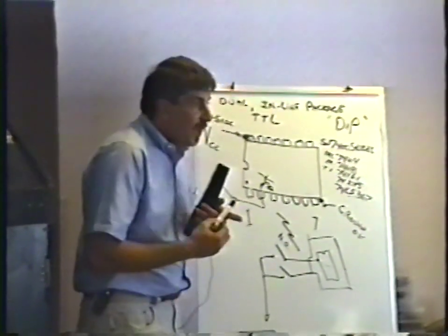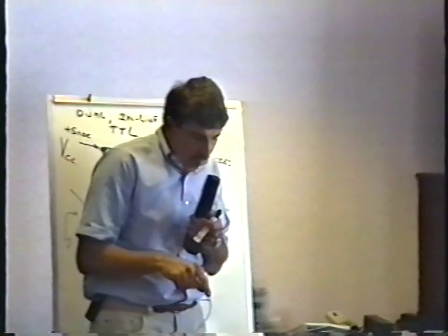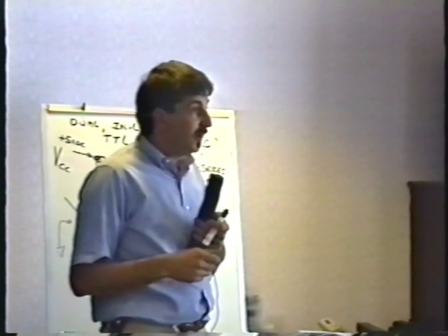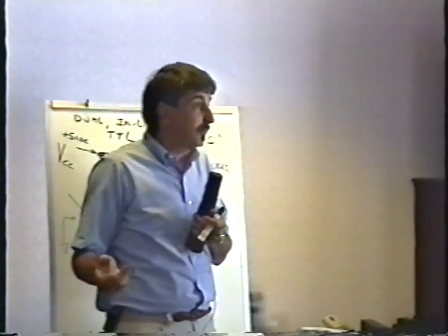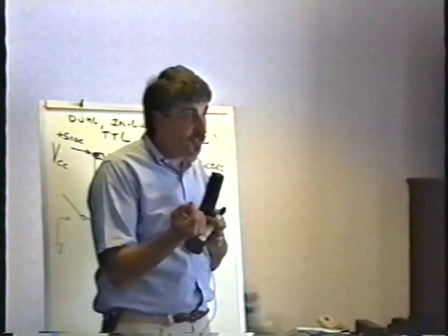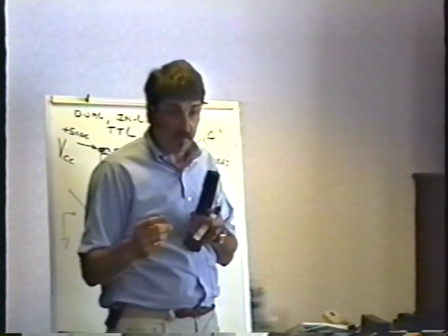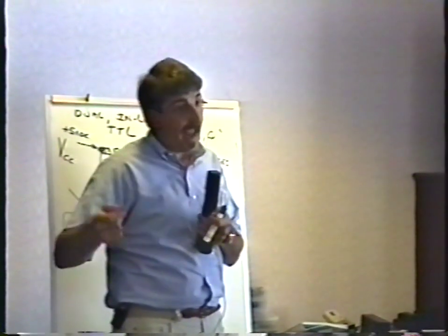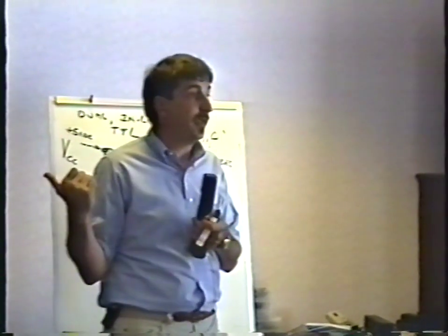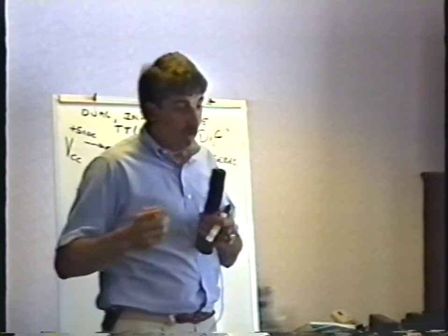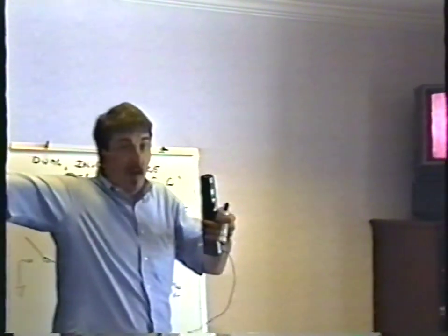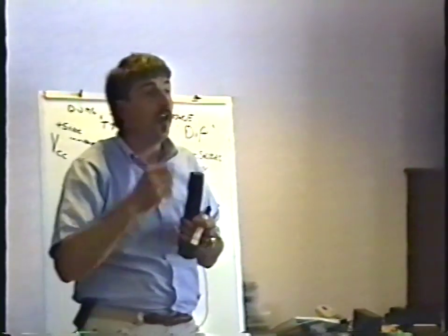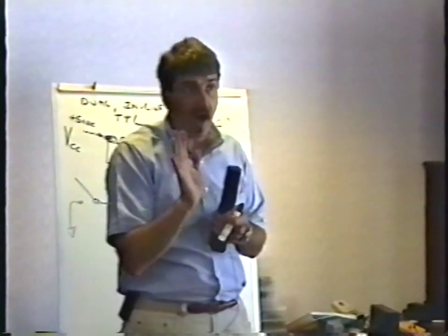Maybe you've seen this. You coin up the game, and you press the start button, and the guy starts to move right by himself, or left, or up, or down. And so you go, well, that's easy. It's a joystick problem, right? So you open up the control panel, you examine the switch for move right, looks perfect. You meter it, it meters perfect. You take the wire off, let the wire hang in the air, you try coining it up, and it still moves right by itself, with the wire hanging off. So you hold the wires this far apart thinking that the air is conducting or something like that. You don't know what's going on, it still does it. You have a board failure. You have an input failure. Very common problem.